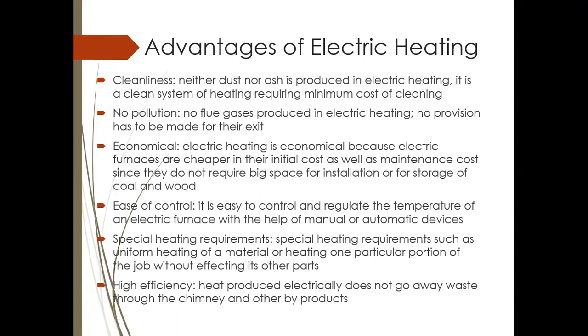Next is ease of control. It is easy to control the electric heating process and regulate the temperature of an electric furnace with the help of manual or automatic devices. The temperature can be controlled within a given range, plus or minus 5 degrees centigrade, which is not possible with any other method of heating.